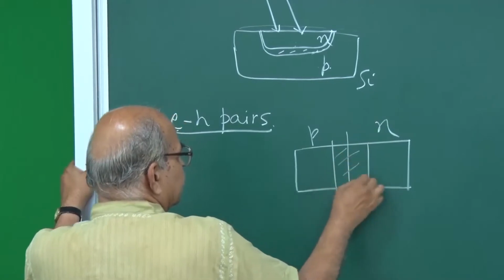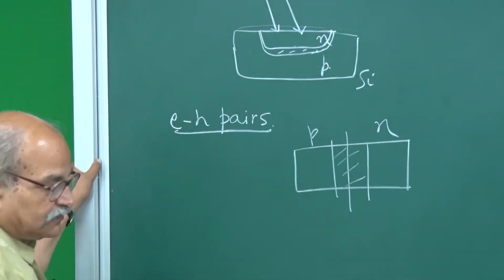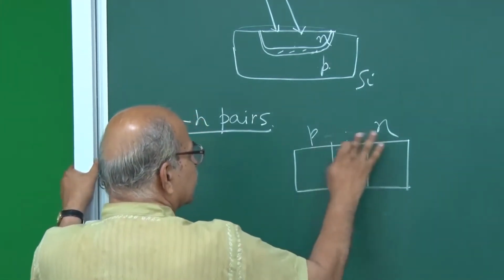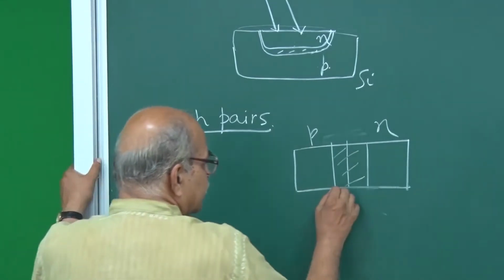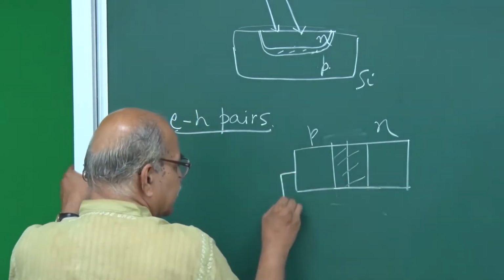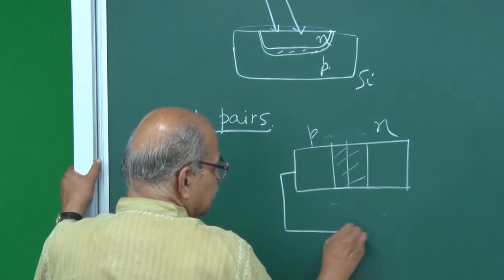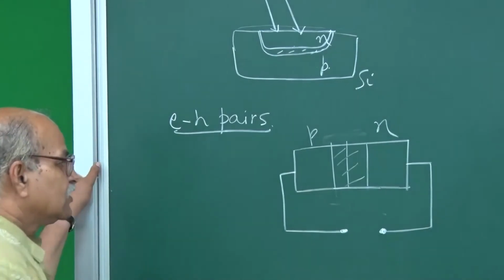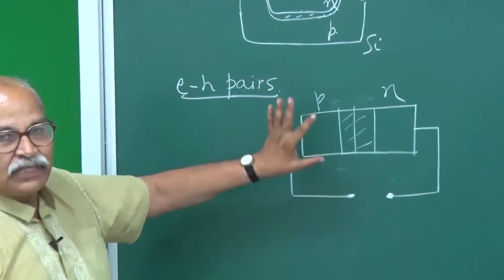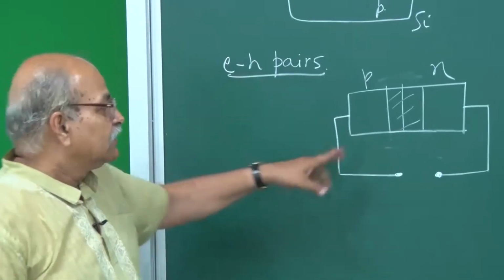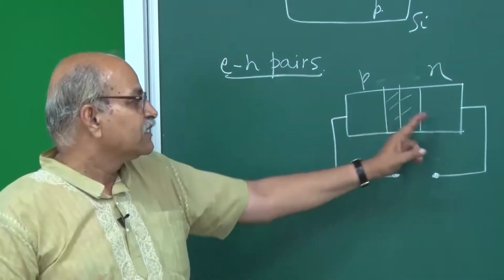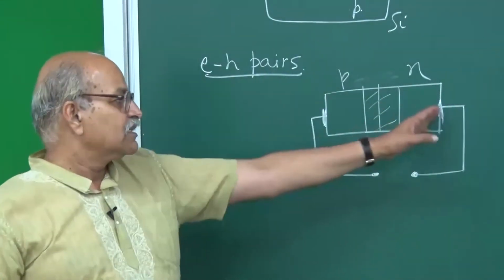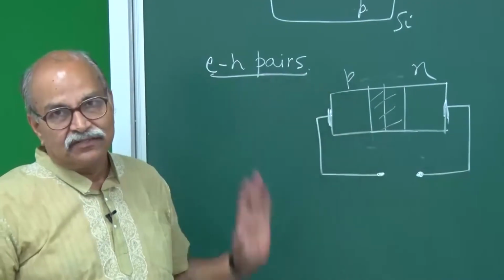and depletion layer. So, you have the internal voltage, potential barrier, and all those things, and let us say we just keep it open, nothing added to it. So, the voltage is 0, the current is 0, everything is fine. Now, you have a potential barrier here, but then you have metallic contacts, and at the contacts also you have contact potential. So, finally, V is 0, I is 0, everything is there.